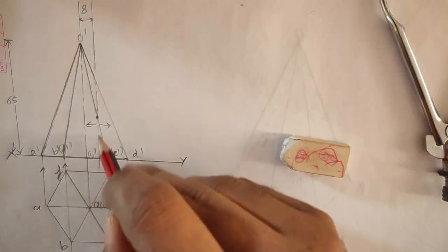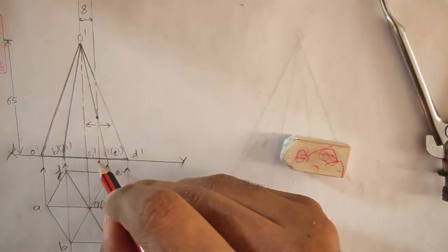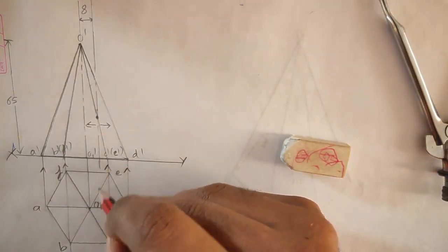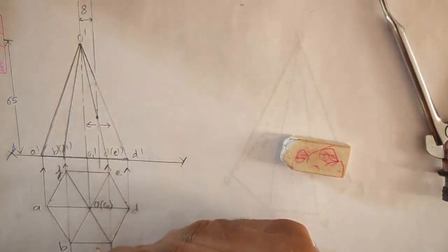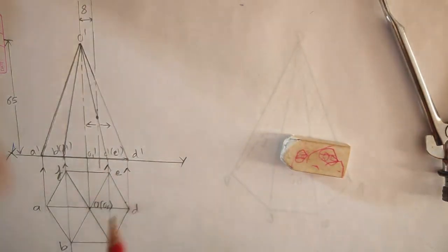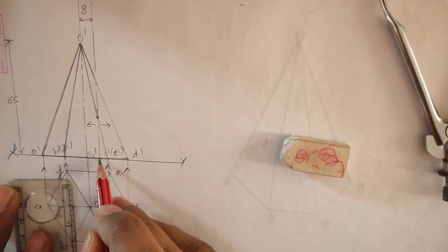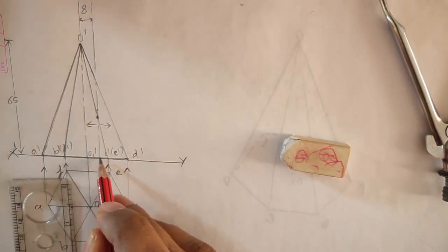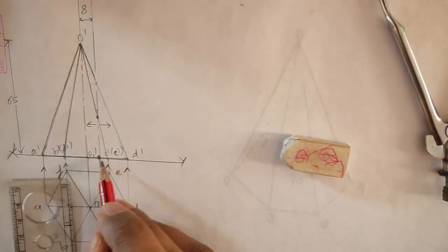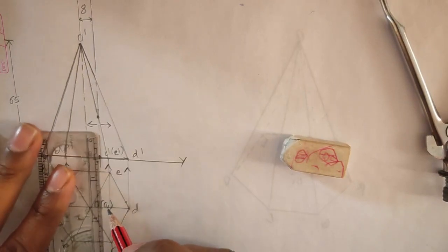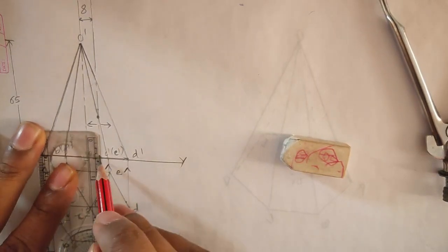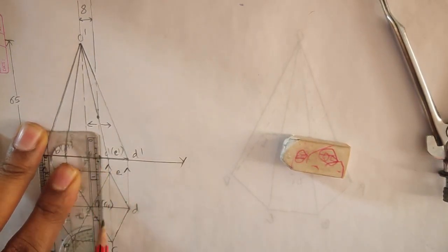But before OC, if you observe, it is intersecting the edge of the base. Now which base edge, you will come to know here. I think you can see it here, it is intersecting at this point here. But in order to know which exactly is that base edge, you need to project that onto the top view.